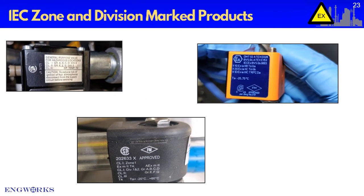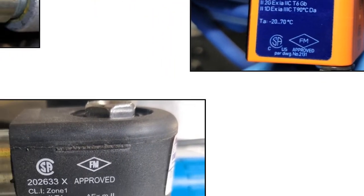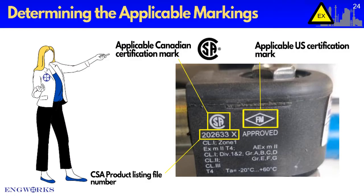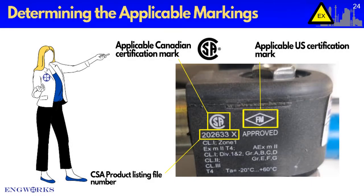This is an example of a zone-marked product. This product incorporates both zone and division markings. Let's look a little closer at this example. The product incorporates both CSA and FM certification marks, as well as zone and division Hazloc markings. The challenge is to determine what markings apply to a Canadian installation.